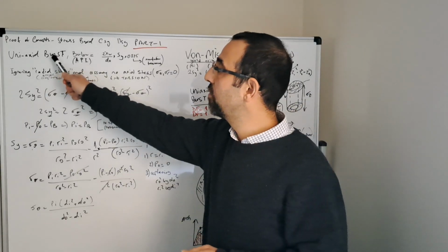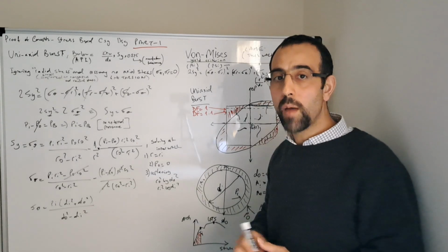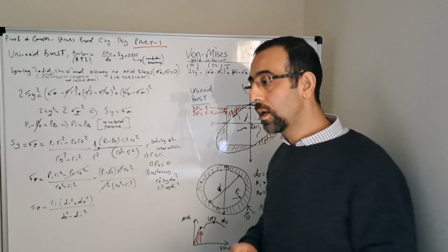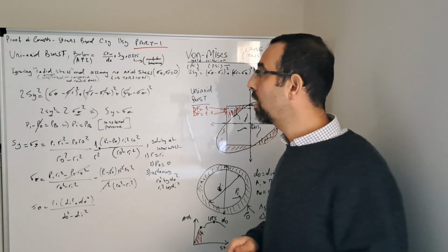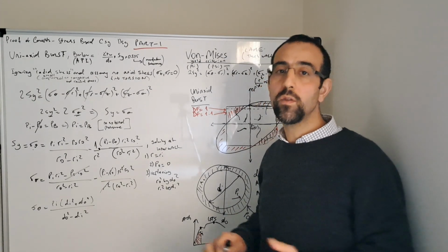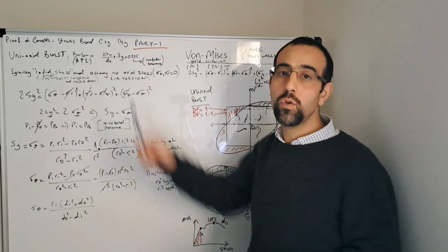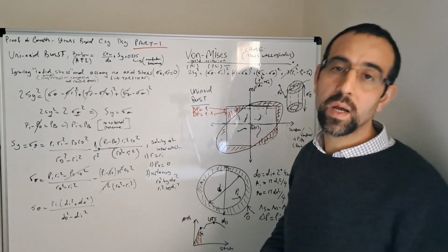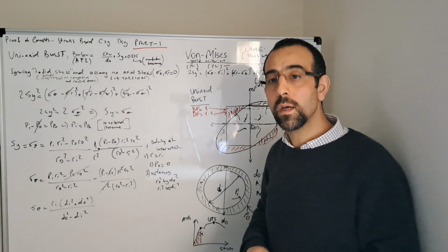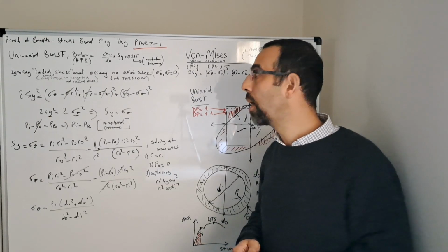So let me clarify, this burst equation is not a limit where basically the pipe will rupture. There are other equations in the literature for that one. However, the API equation, a kind of Barlow equation, is the widely known solution, and also is quite practical to use, although it might set a lower limit. So it's the start of the yielding. It's not yielding somewhere in the cross section of the pipe.